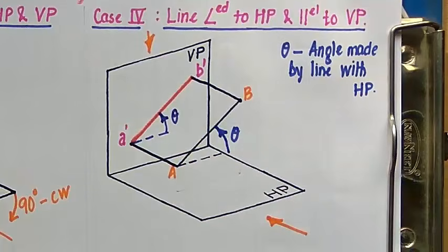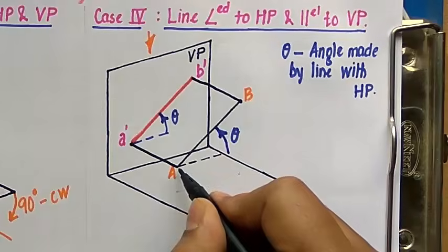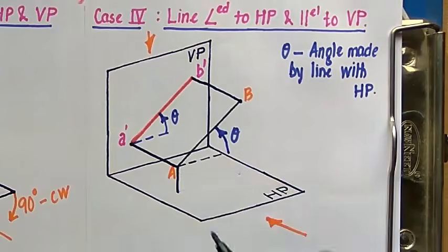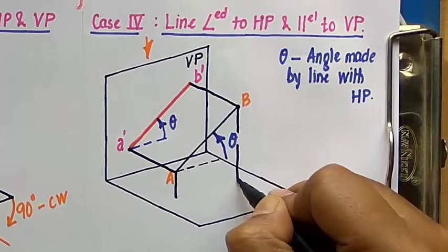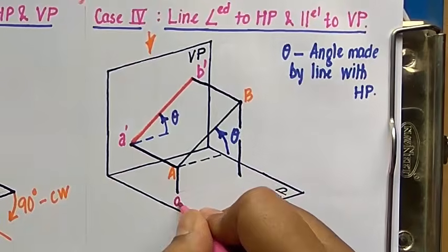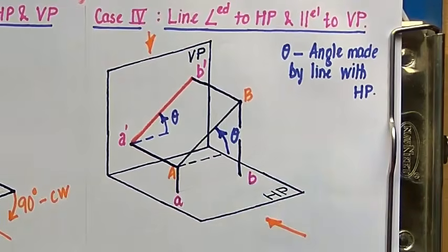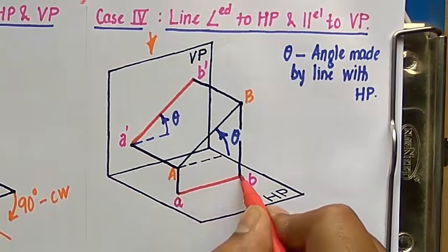Fine. Now similarly, we are going to look at this line right from the top, and on looking at it, we'll get the top view. All right, so on extending this line in the downward direction, it will intersect this horizontal plane somewhere here. Let us work this out. So this is going to intersect over here. So the intersection points are A and B, and when you join this A with B, you'll have a view that is what you call a top view.